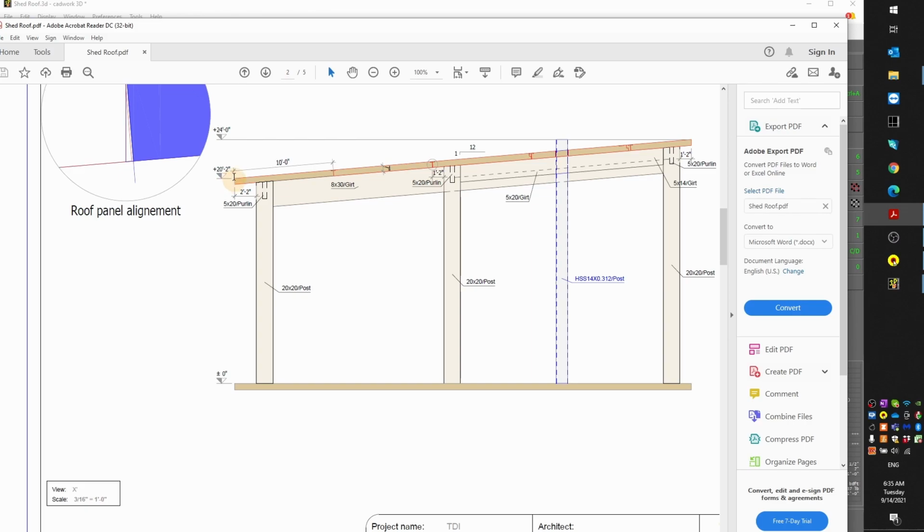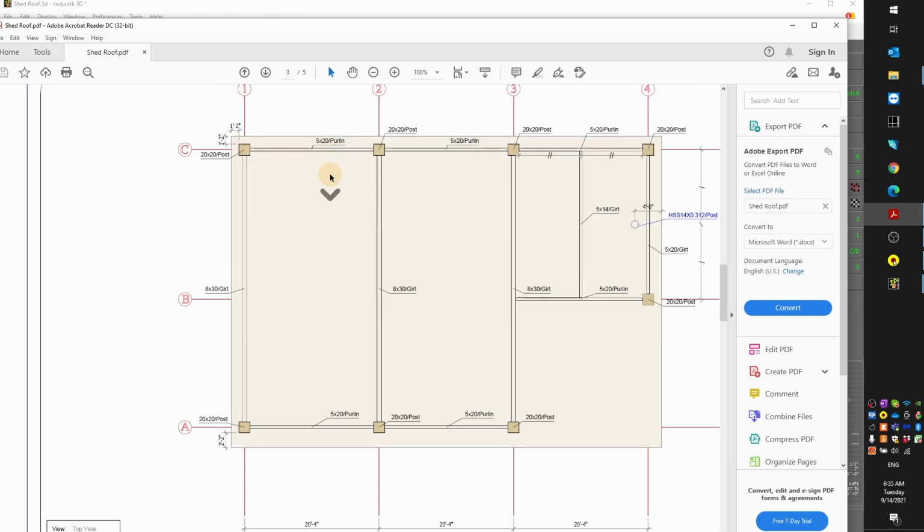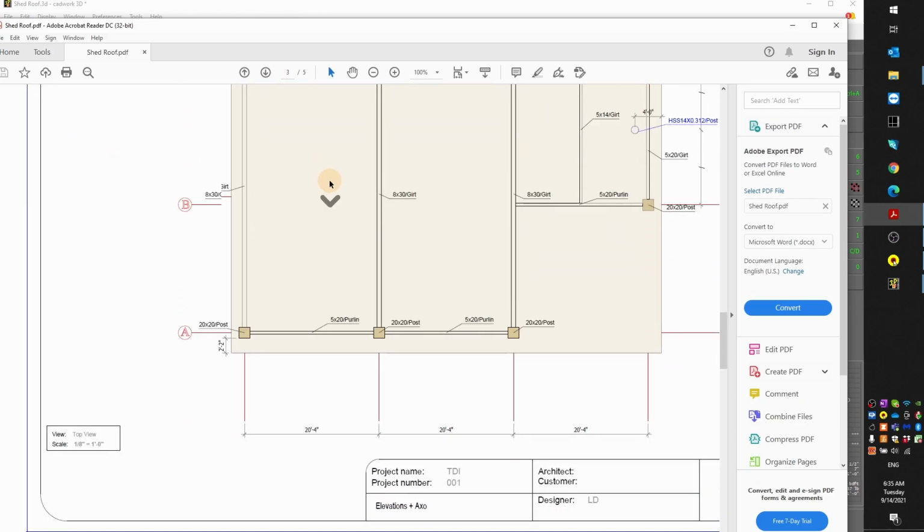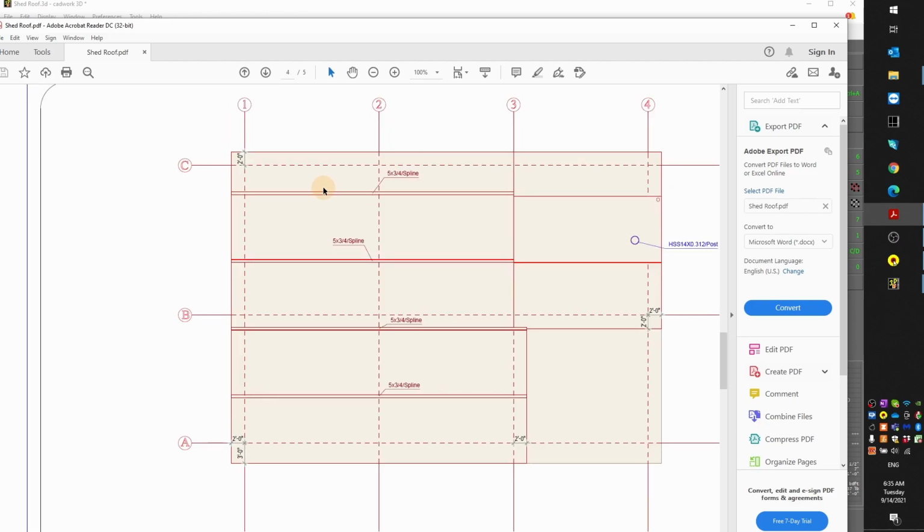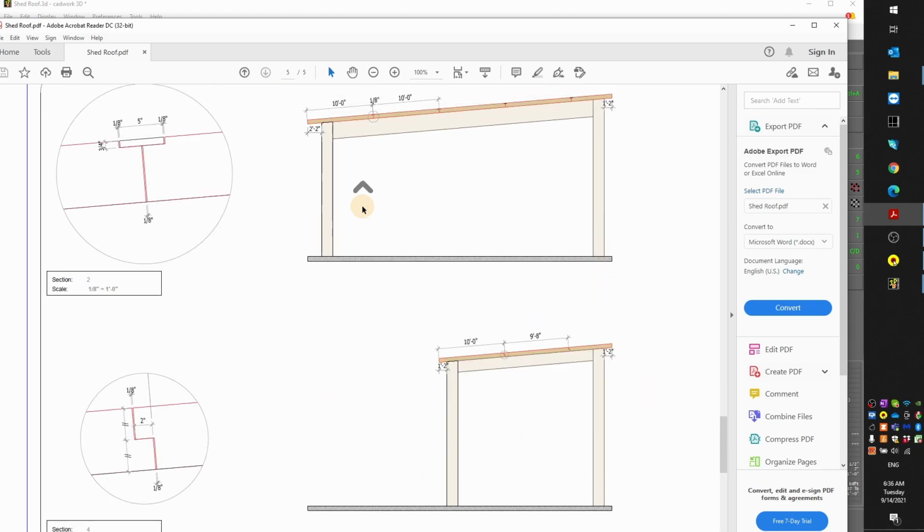So we see here that these panels should be 10 feet wide. So there are different ways of doing it, and we are also working on a new feature to be able to cut these panels in a series with the right tolerance. We see down below that we need a tolerance, a space of 1/8 of an inch. Note that 1/8 of an inch is the bare minimum. I think it's better to have a little bit more tolerance, but it always depends on each project.